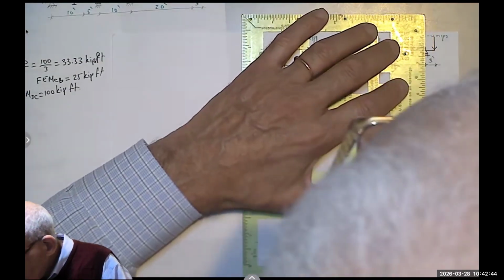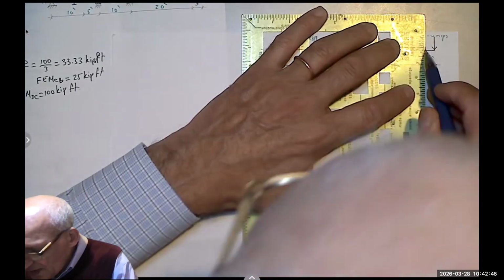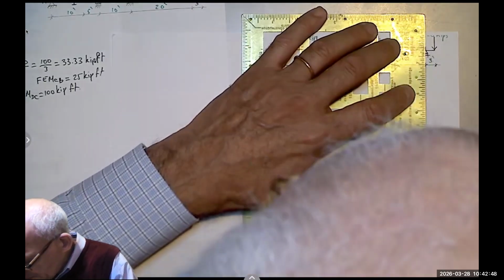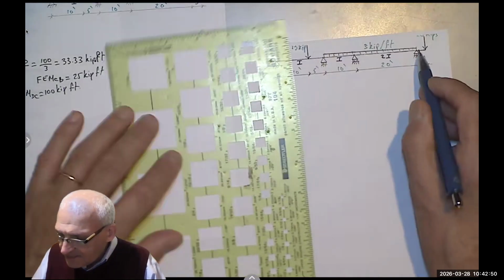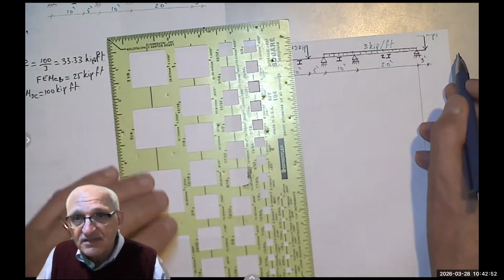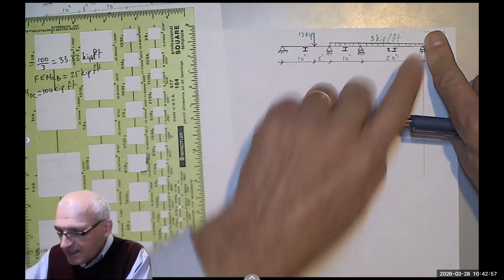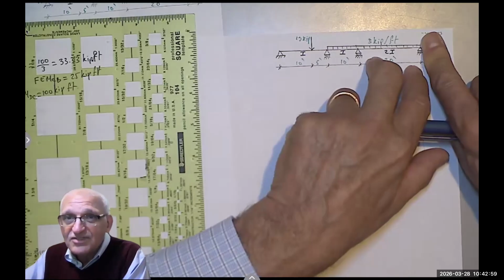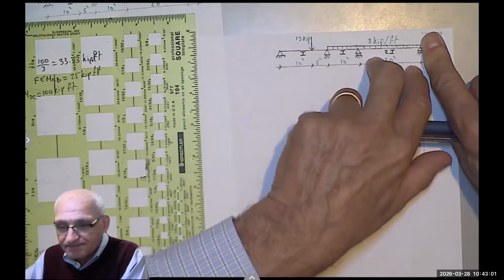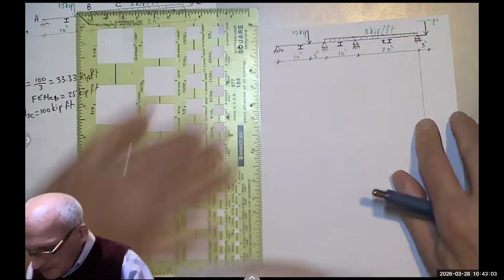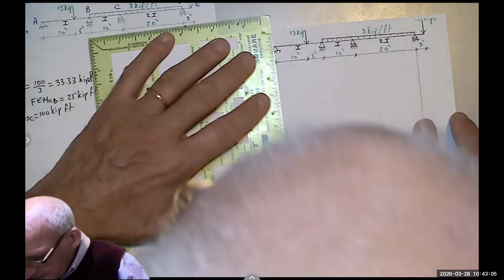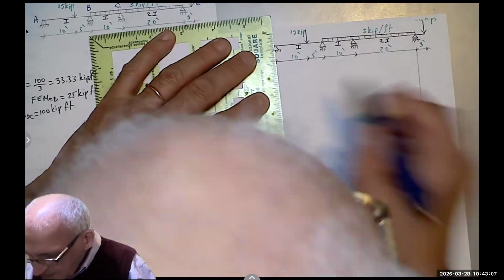We don't need the cantilever now, and that's why we assume this is fixed, by the way. Some people will say, but isn't that the end point? No, it's not, there is a cantilever. That's why it's not the end. If I didn't have that, then both of these would be similar, and I would say 3 times 2 over L for the relative stiffness.